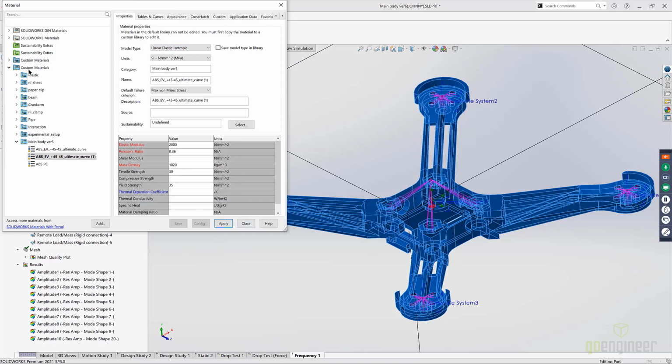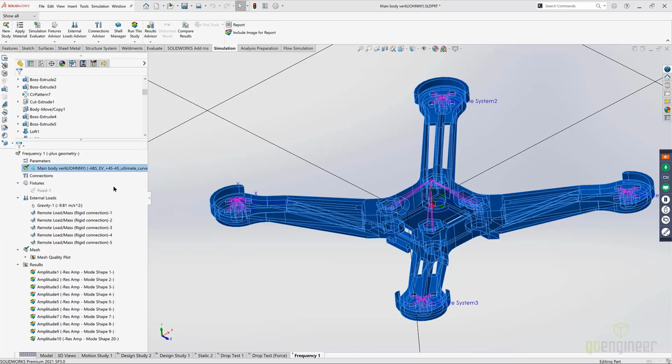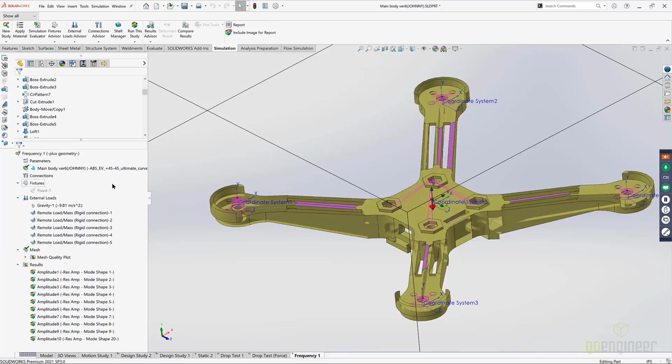And as a side note, if you have two custom materials folders, you may need to check which file location you're at just by hovering over it. If you have one in Program Data, and you move all of that data to another computer or you reset that computer, you'll lose all that, so you just have to move it to another folder. But this is where you can apply either the standard plastics SOLIDWORKS has provided, or you can input your own materials that way.